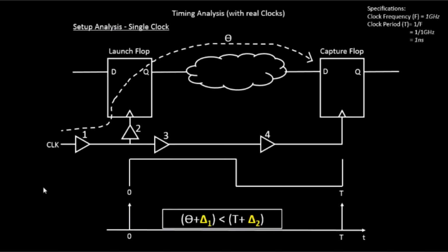We'll come to this Q equation in some time, but before that, this is the equation that comes up in the presence of a clock network, that is, a clock tree that is built from this point to the clock endpoints, the tree that we have been building so far. The buffer delays come and sit over here. So this is where the timing gets impacted.